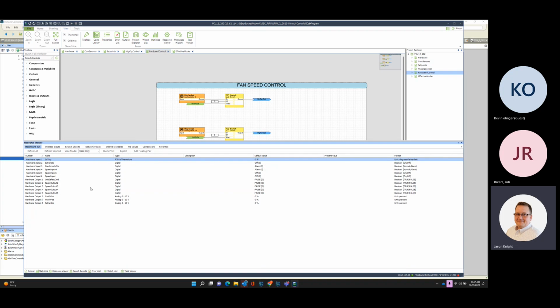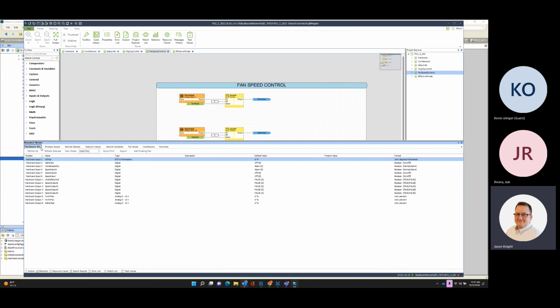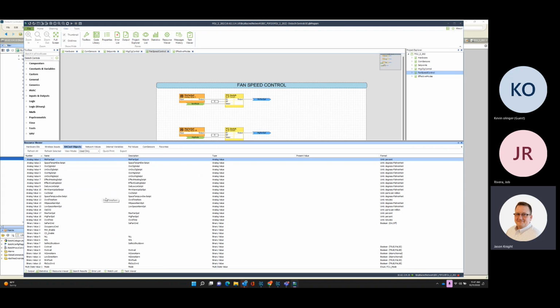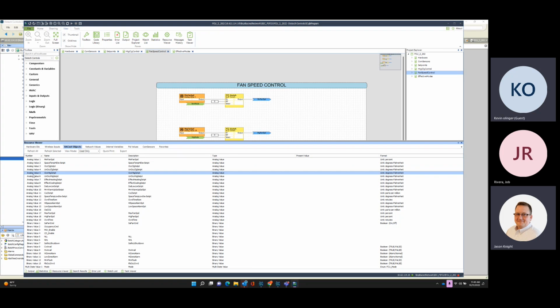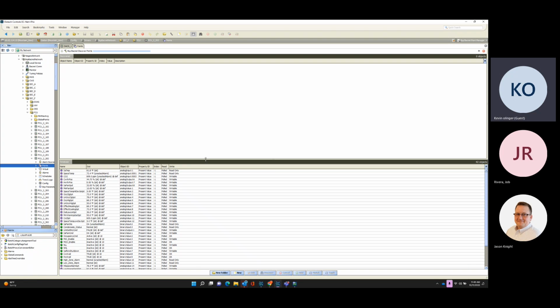On some more of the advanced training we'll do later on, have you done any of the stuff with using the resource viewer, hardware IOs? Like if you have a wireless sensor you've attached to it, or if you want to see the BACnet properties that Niagara's looking at, or let's say you want to hunt down an AV or BV, and maybe sometimes it gets mapped wrong, and you're like, oh, well, Niagara's saying its AV5 is like the unoccupied heating set point. And then you launch your program, go back into it, and go to your resource viewer, BACnet object. Oh, AV5 is actually the occupied heating set point. So let's save that for the advanced stuff. Yeah. Pretty much all the GFX stuff.